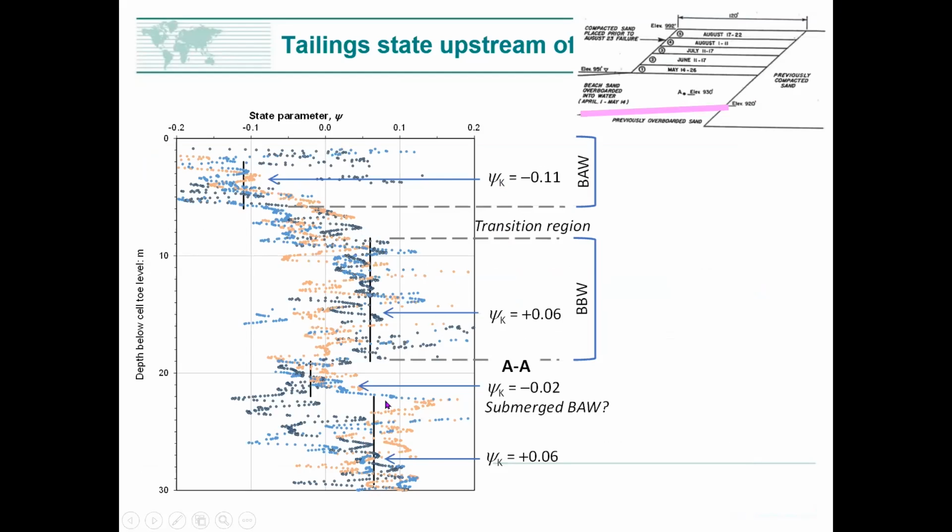Originally, I wanted to go with a little bit over here, and I suggested 0.065. And my co-authors probably properly said, Mike, you're full of it. You do not have 3 decimal place precision on this kind of judgment. So we actually ran with 0.06. So that's what we put into our Plaxis model.